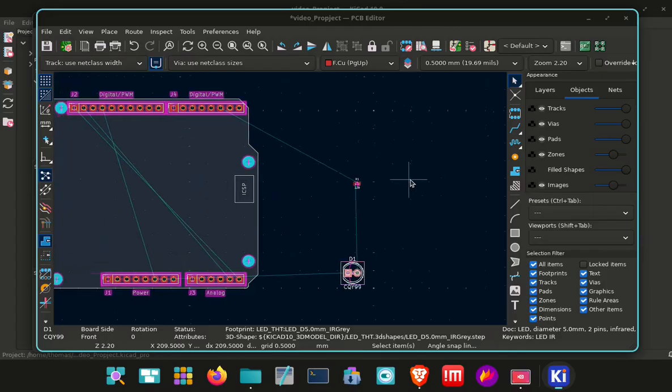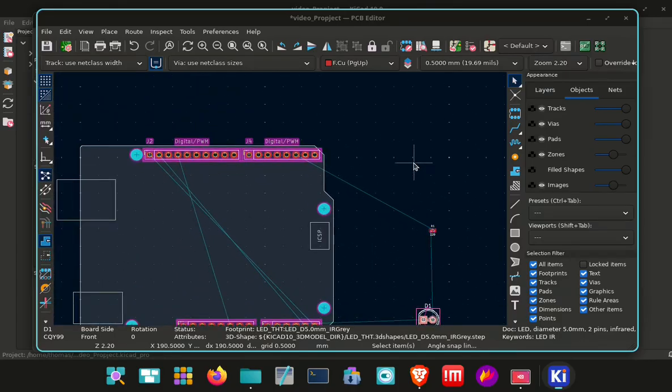So now we have our pin 6, and it's telling you which pin it's connected to. The circuit then goes to a resistor, it then goes to the LED, and it then goes down to ground. Now we need to actually make tracks so that they can print them, or if you're going to stay around for the next bit, then we will 3D print this, and then use copper sheet to make our own circuit.